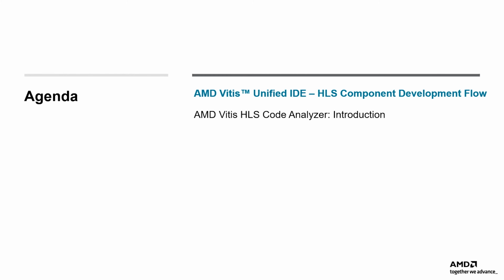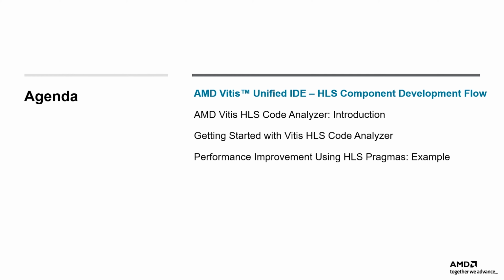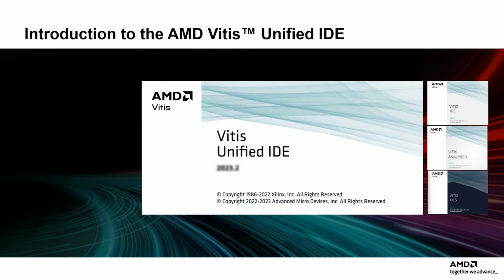We will focus on the HLS component development flow in the Vitis Unified IDE, introducing the Vitis HLS Code Analyzer tool, how to get started with the Vitis HLS Code Analyzer, going through an example of how to improve performance using Vitis HLS Pragmas. The Vitis Unified IDE is built on the open-source Eclipse Theia framework, providing a robust and